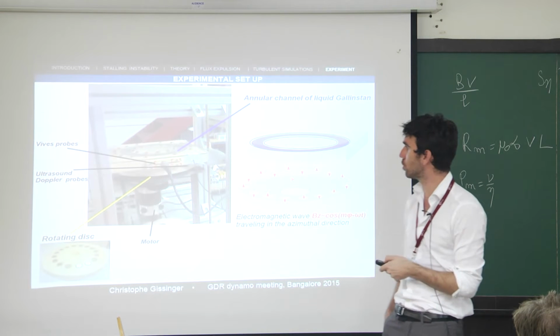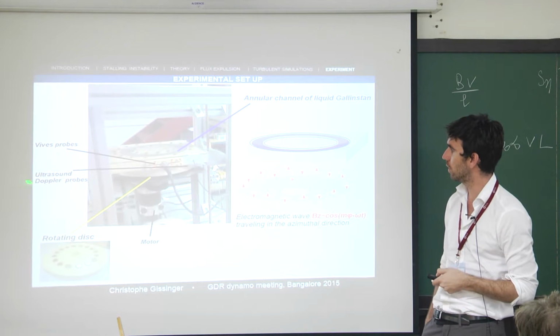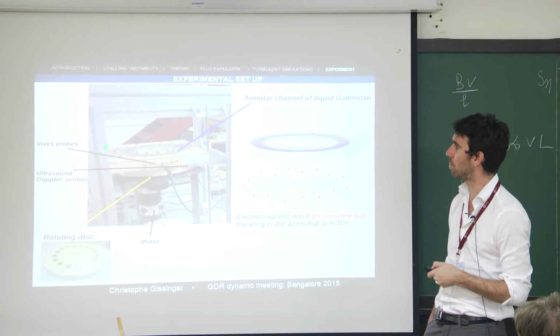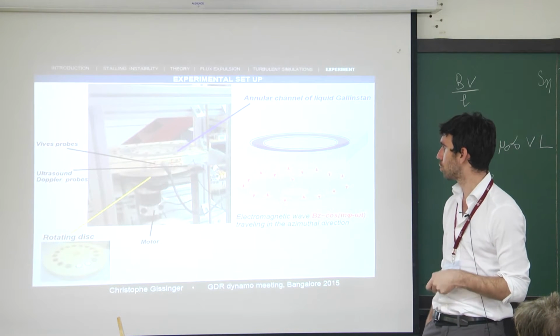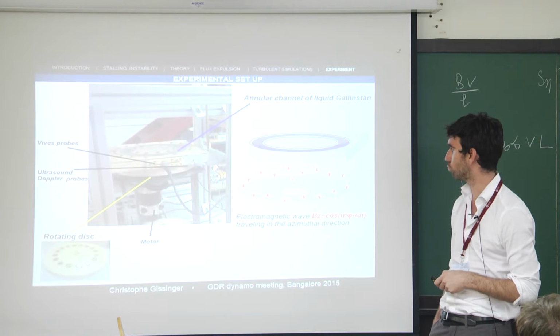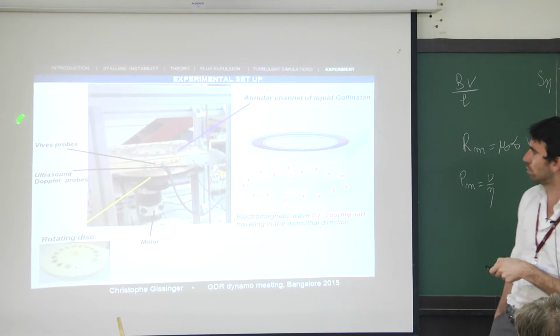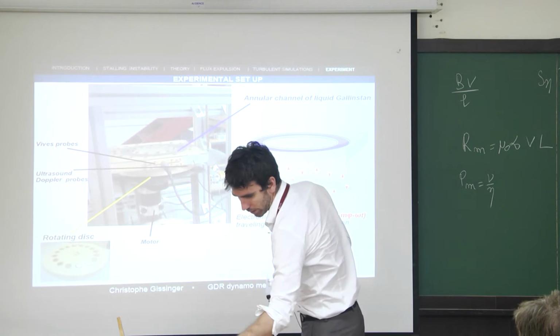That's the idea. To measure the flow, we're using ultrasound Doppler measurements. We also have some potential probes. We tried a pressure sensor, not very successfully. But these two are enough to characterize the flow.